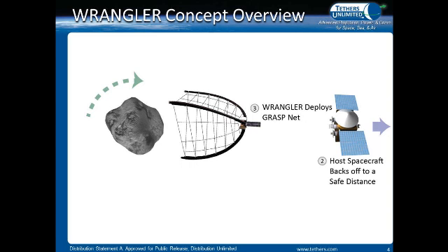The main reasons for going that route were that a net compacts much smaller, and we were looking at using very, very small, CubeSat-scale spacecraft to grab onto very large spacecraft. Though we looked at using a bag or something of that nature to capture debris, it just doesn't pack as well as a net, which can have a very sparse, low-density construction.